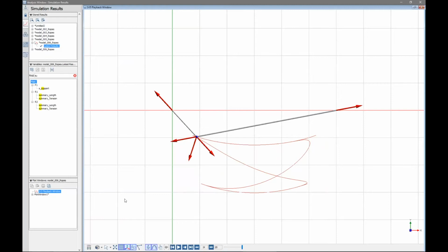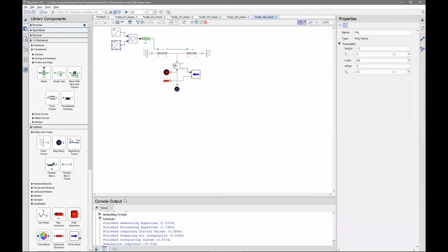So these last two examples show that if you want to change the length of a multi-segment rope, you can grab one end or both ends, depending on your case, and move them, or you can use the 1D connection to add or remove rope from your system. The same would apply again for chains and cables, except that ropes would be the simplest and leanest model that you can create. Your fidelity requirement will dictate which one of these would be needed. We'll talk about chains and cables a little later.